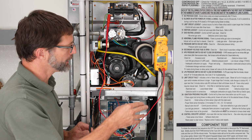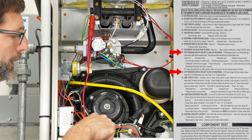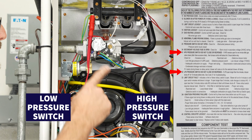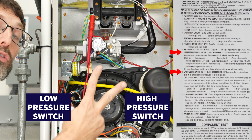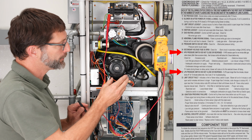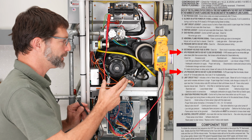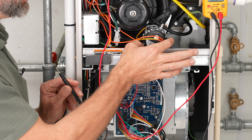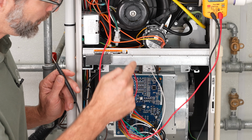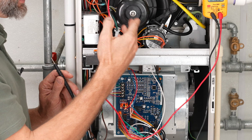Error code status light 31 and 32 have to do with these pressure switches. And so this is a high pressure switch in the front and a low pressure switch in the back. Some of these gas furnaces that only have a single stage gas valve may have two pressure switches. And one may be measuring straight to the inducer motor, and one may be measuring over to the condensate trap. And so regardless of whether it's a 31 or a 32, basically the long and short is that the circuit board down here never got a signal back saying a closed circuit, meaning the inducer motor is not running when it should be.